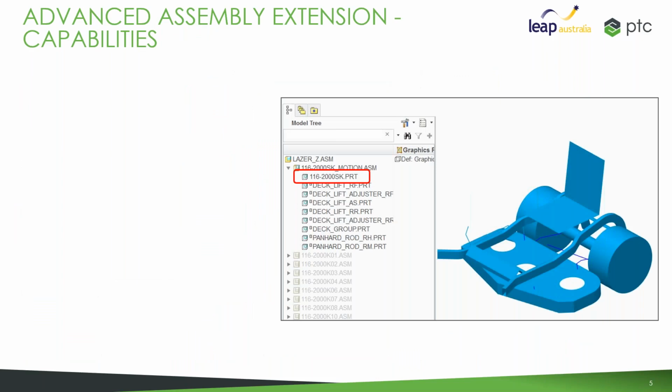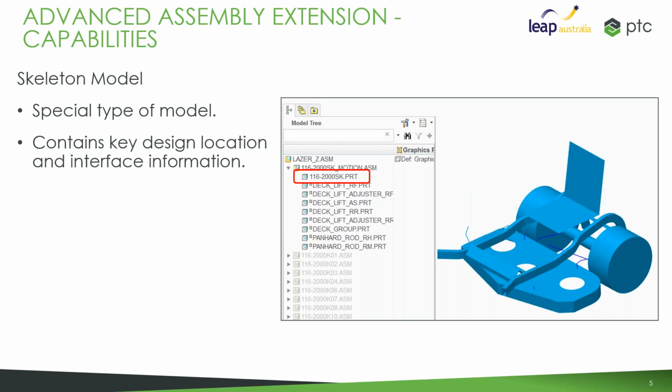One of the key elements of the top-down design approach, which I explained in the third stage, is skeleton modeling. The team leader can build critical geometries that actually drive the other parts and the sub-assemblies. So it's easy to plan the framework of an assembly and make seamless changes that automatically propagate to the reference components.